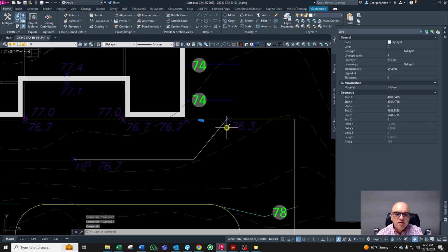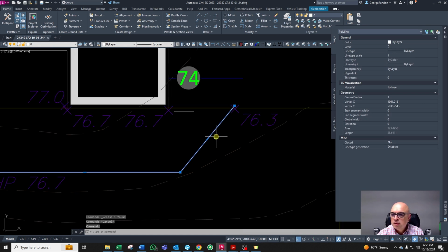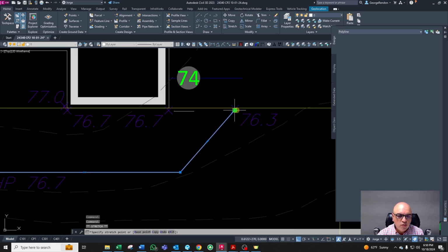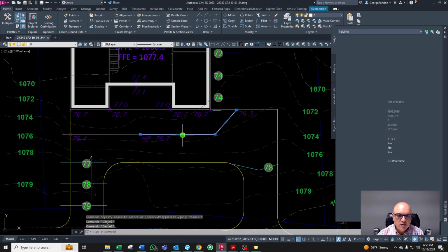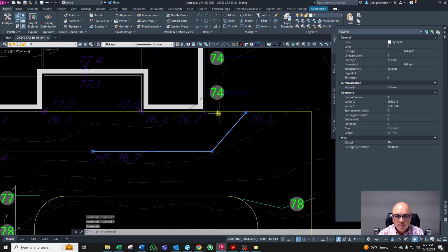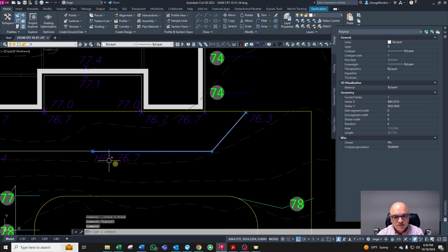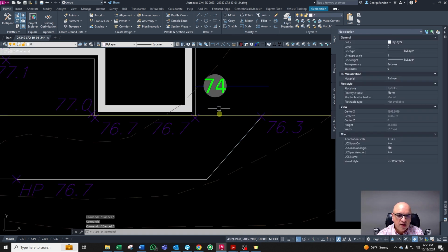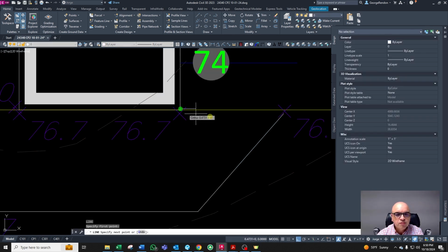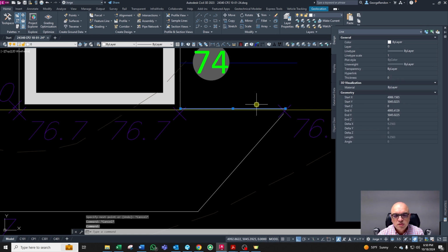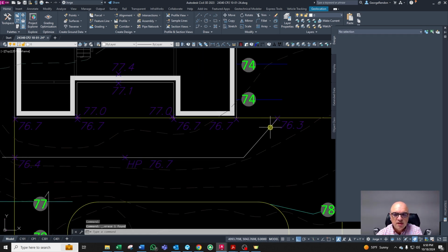Now this swale is 40 feet away from the high point. So this swale is okay, because it is at 1%. This swale is 4% from the high point, and from the corner of the house is less than 5 feet. But remember, the maximum slope over here is 5%. So this is fine.